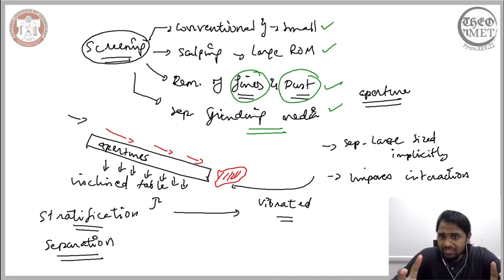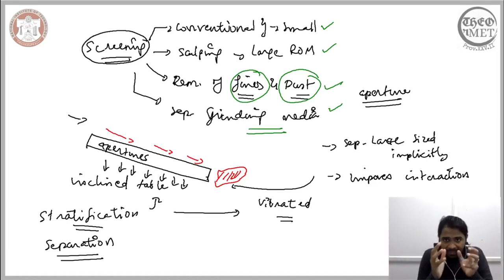However, the dust plays a rather detrimental role, whereas the grinding media play a critical role in the particular process of comminution. However, their role is rather limited to that grinding process, and therefore they need to be removed after the desired reduction ratio is achieved. This removal of the grinding media is done by a process similar to that of screening, and therefore it is also categorized under screening.